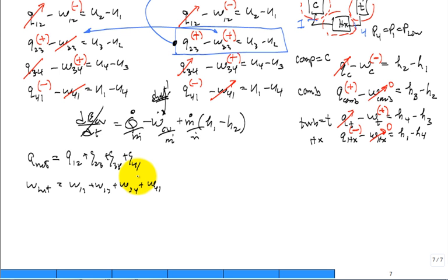And when you're doing these calculations, should these two be equal? They are the same. Please check, check, check. Have you solved some problems and then checked them and said, oh, I'll go find my error? I got an error if they're not the same. The metric of interest is the thermal efficiency for the Otto cycle. What would that be? Would it be the net work out divided by the heat in? Where is the heat into the cycle? Q2-3. That's the only heat in.